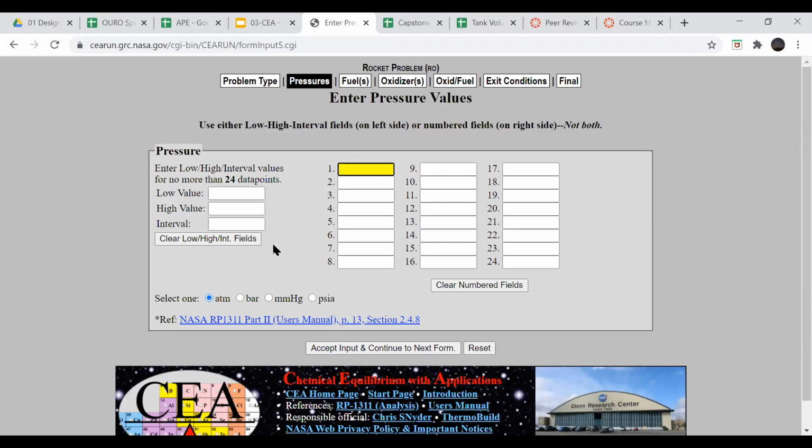Like basically, a higher chamber pressure tends to provide more thrust because of the way the expansion works in the nozzle. So generally the higher chamber pressure is desired, but there are drawbacks because that means your nozzle tends to be bigger, and also you need to be able to hold more pressure and supply more pressure, so you end up with more weight. So as far as what we're doing right here, it's basically to build a spread of pressures so that we can see what the combustion efficiency losses are if we use a lower pressure, because sometimes using a lower pressure is still going to save us overall efficiency because we can build with lighter materials or have a cheaper feed system.